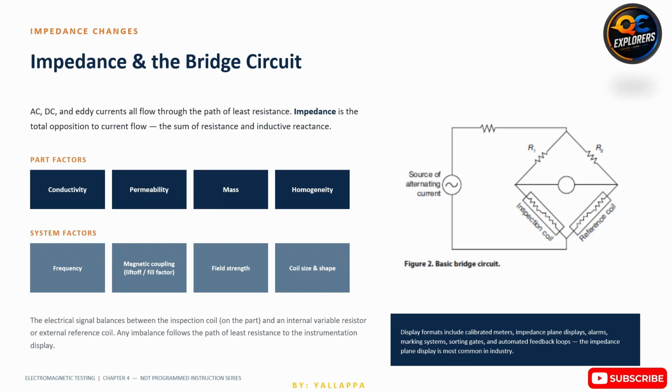the material. Another important factor is magnetic coupling, often influenced by liftoff and fill factor. Liftoff is the distance between the probe and the test surface. Even a small change in this distance can significantly affect the signal. Fill factor describes how well a probe fits around or inside the component. Better coupling results in stronger and more stable signals. Field strength and the size and shape of the inspection coil also influence the sensitivity and inspection coverage.